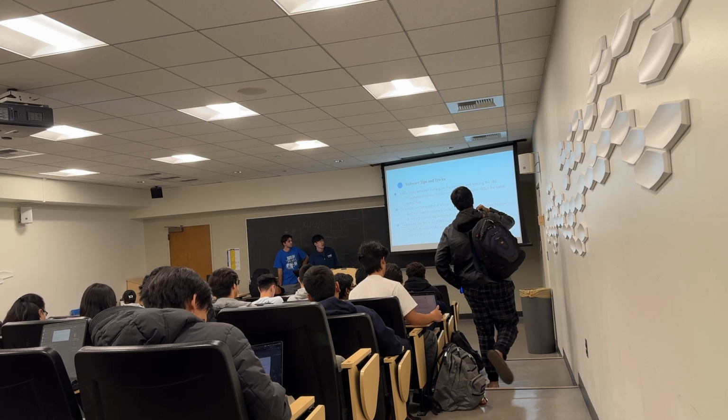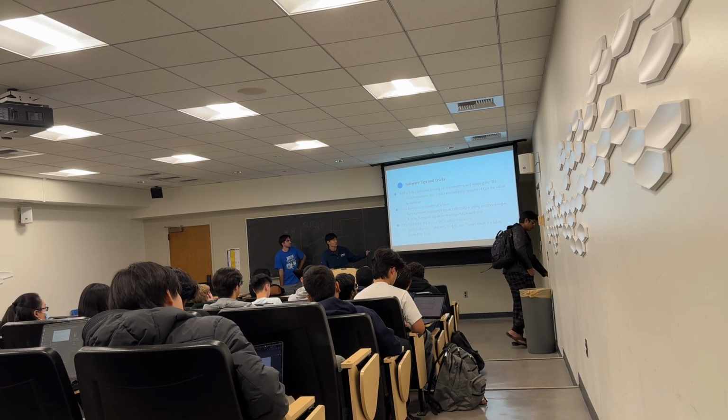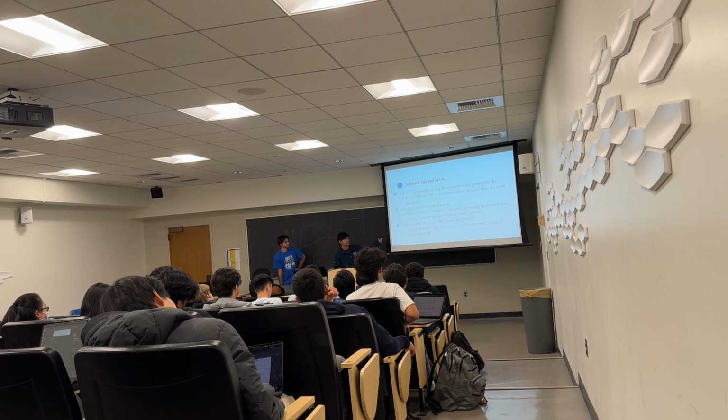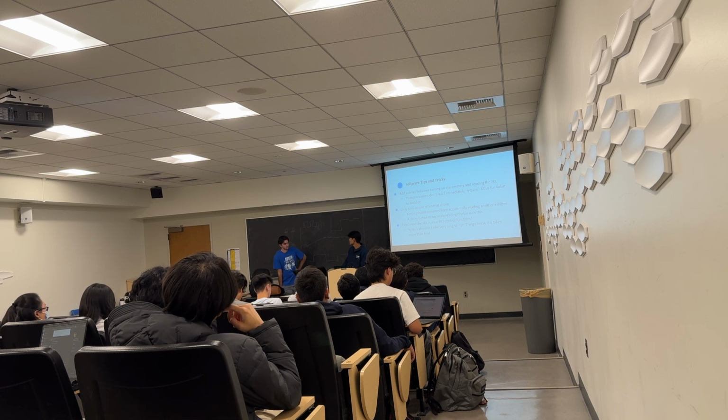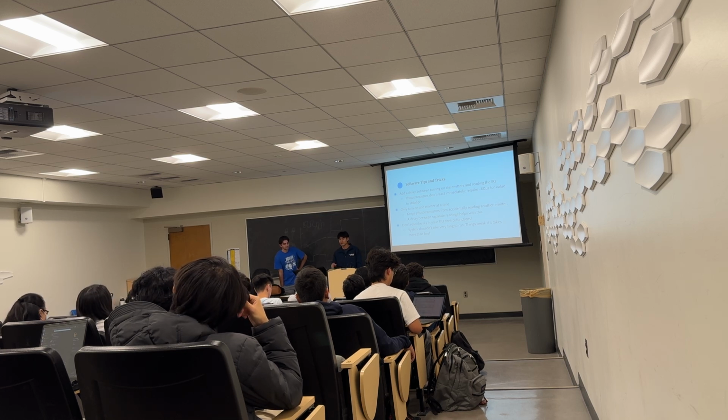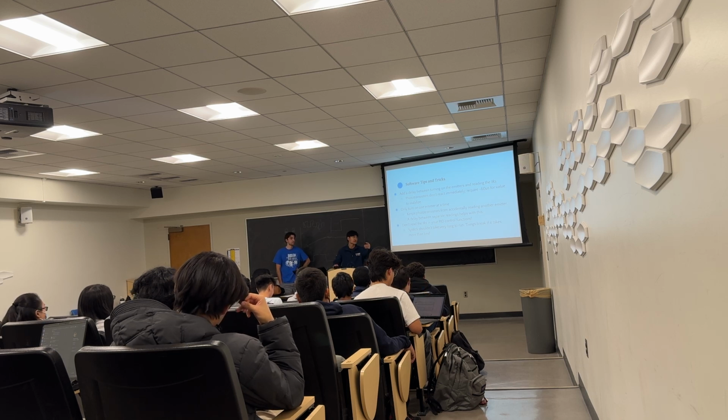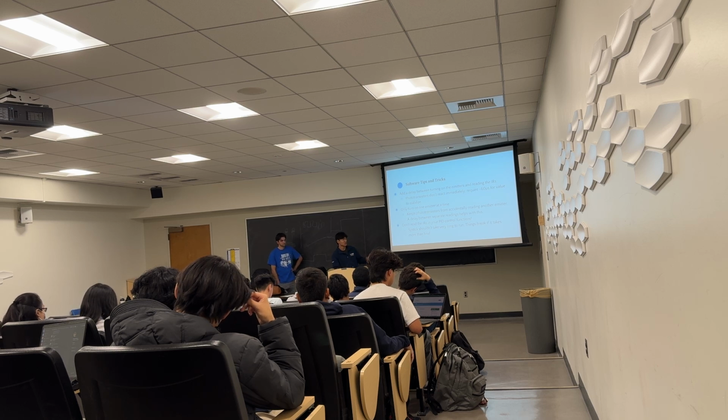Last thing is, don't read the IRs in your PID control functions, because SysTick shouldn't take very long to run. SysTick basically allows your functions to run every millisecond, so if you want to do something continuous, you do it there. But reading IR values might take more than 1 millisecond, so you want to do that outside, or else it might break things.